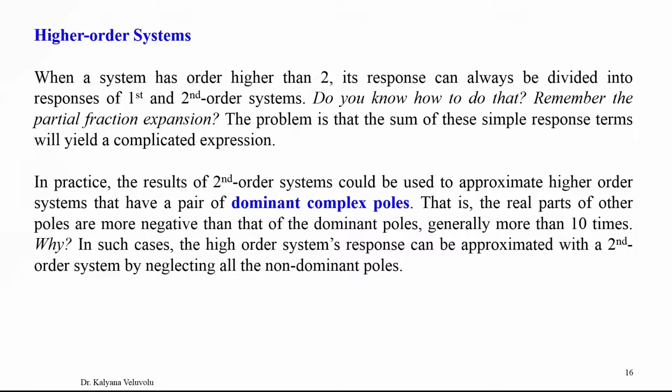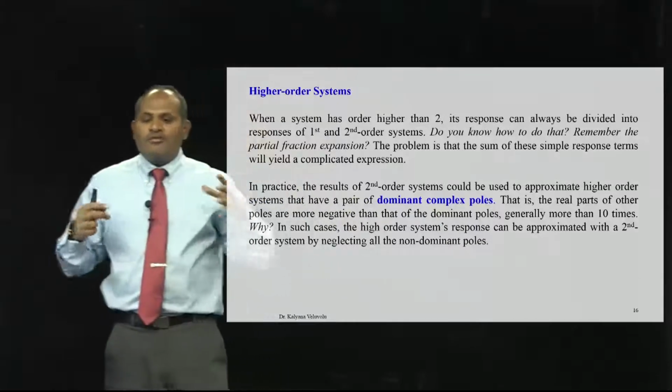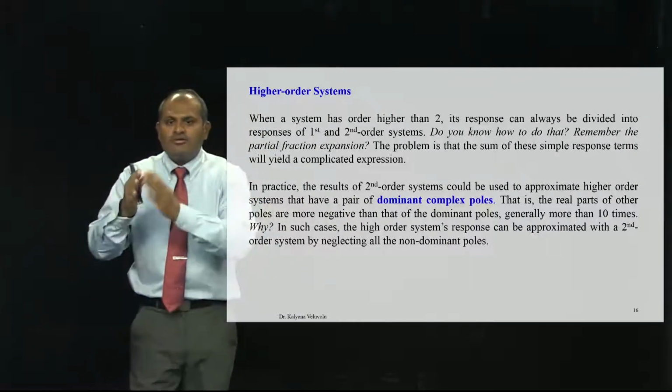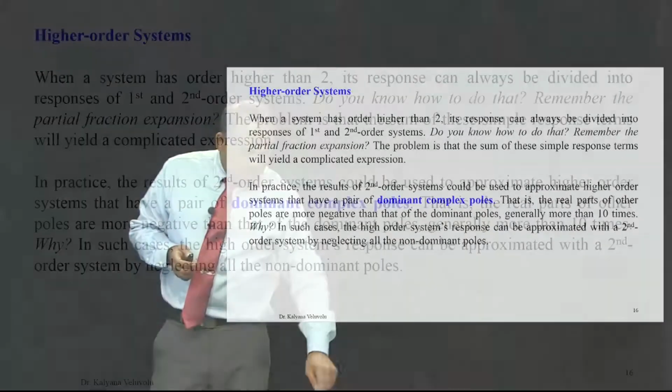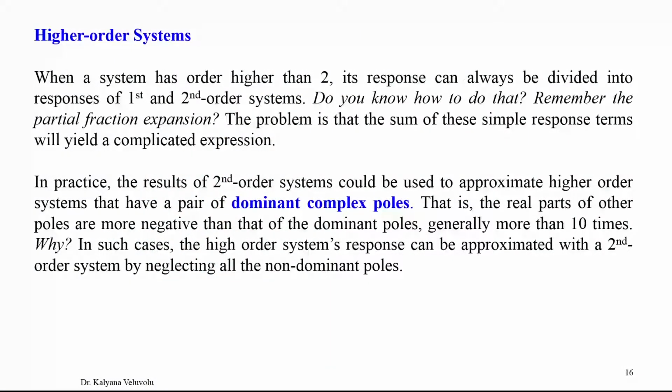When you have a third order system, I can convert the system into first order and second order systems. So, using theoretical tools, we can always break an nth order system into individual responses. In practice, the results of second order systems can be used to approximate higher order systems that have a pair of dominant complex poles.